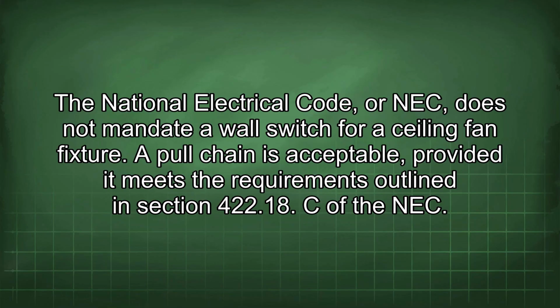The National Electrical Code, or NEC, does not mandate a wall switch for a ceiling fan fixture. A pull chain is acceptable, provided it meets the requirements outlined in Section 422.18 C of the NEC.